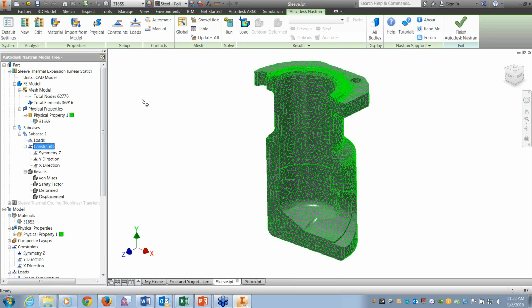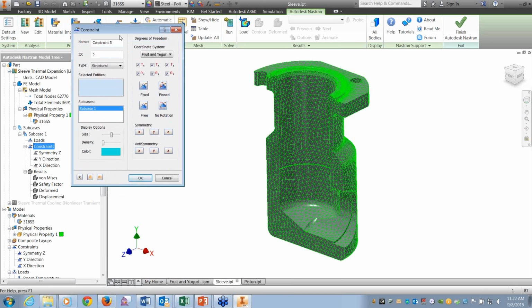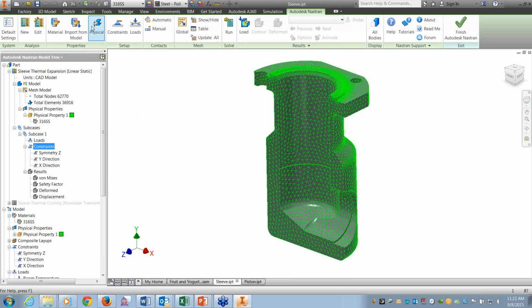So the workflow, classic ribbon workflow, we would start at the left and work our way to the right. This is an existing analysis. The materials have been brought over already. Something that's always been a bit of a challenge with Inventor is being able to allow for simplification of the model, where you can say that you're going to do, let's say, a fixed constraint. That one's fairly straightforward. I could do a fixed constraint on a surface and pick another surface to simulate a bolted connection, if that was appropriate here. Or, you can see it's already labeled here, but I'll go ahead and recreate it.